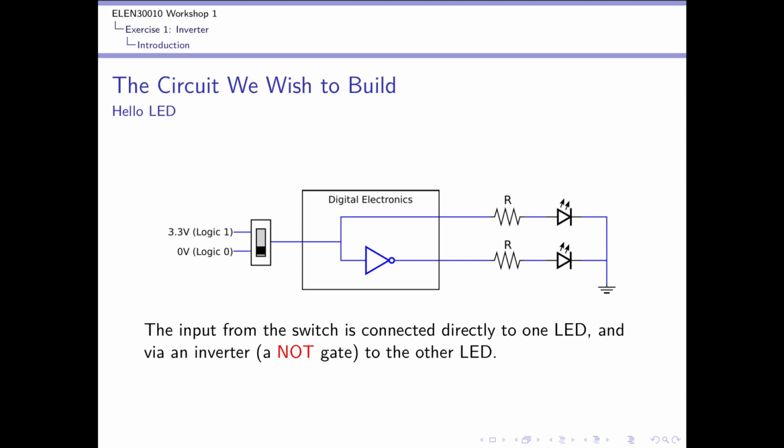But in case you're wondering, if I'm able to put exactly half of a voltage, halfway between 0 and 3.3 volts, in here, then if this is ideal, I'm going to get out exactly the same voltage here, halfway between 0 and 3.3 volts. That's an analog phenomenon because this is at the heart of it an analog device, but we don't use it that way. We only really care about what happens when the input is either at 0 volts or at 3.3 volts. And what should happen is that it just inverts it like that.